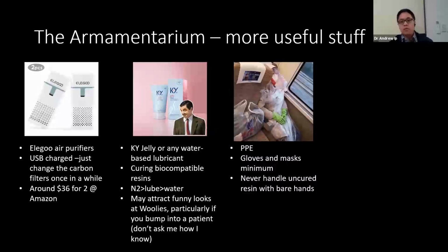Now, you will need lots of PPE. Gloves and masks, you will need them because you really do not want to handle any of these resins with your bare hands. So make sure you glove up, mask up. Don't be afraid to chuck gloves. You will burn through them. Unfortunately, it is part and parcel of resin printing.